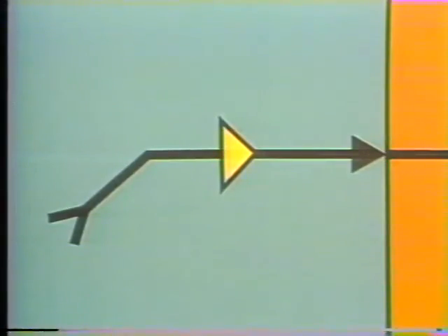The symbol for a weld joint on a machine is an arrow like this, pointing at the weld itself. This arrow just tells you that there is a weld. You have to add another symbol to the arrow to explain the kind of weld. This is a bead weld symbol, a fillet weld symbol, and a V-groove weld symbol.